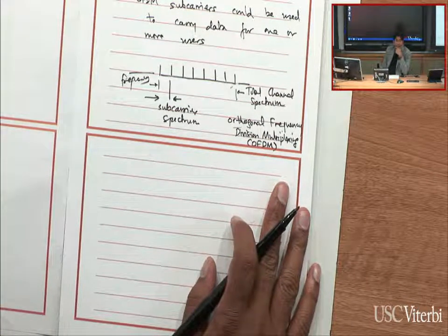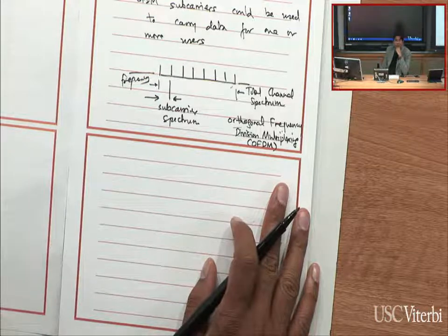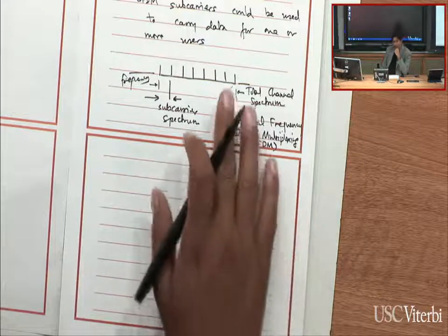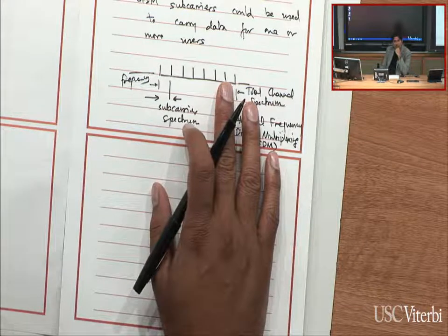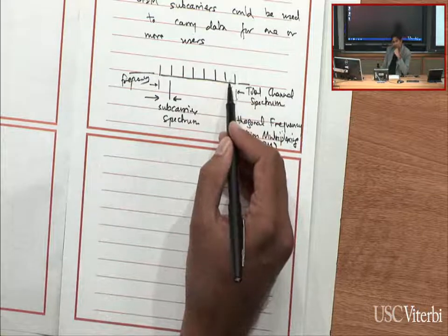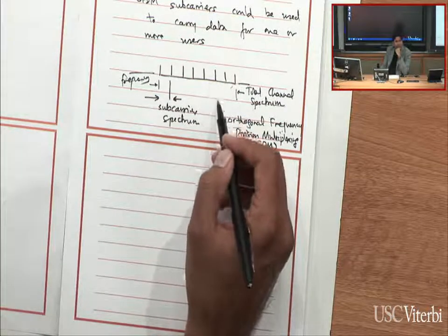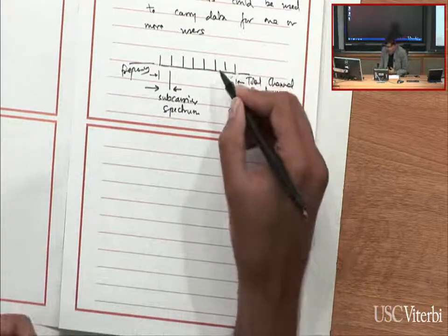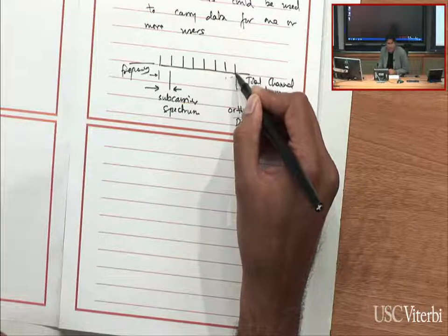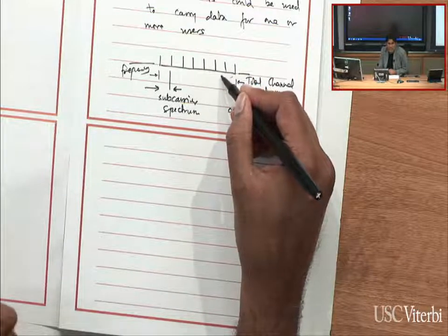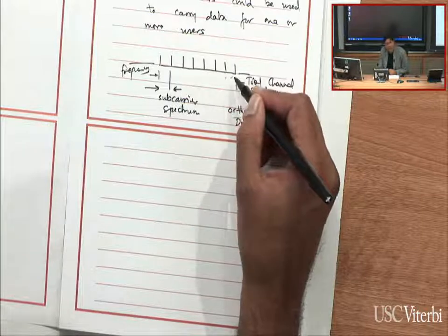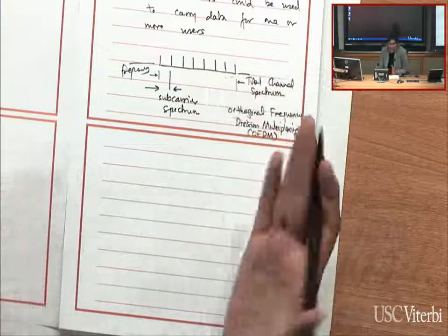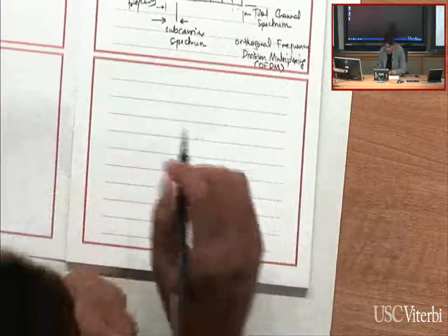And it may have been a marketing term because in CDMA, if your codes are not perfectly orthogonal, they may cause a little bit of interference between users. Whereas in theory, at least, if your transmissions on each frequency are kept within that subcarrier, they really should not interfere with the other carrier. Now, in practice, even that's not entirely true because anytime you're actually sending a signal over a certain frequency range, there's typically some side lobe, some residual bit of leakage of the power from one portion of the spectrum into others. So it's not 100% orthogonal anyway, but those may have been reasons for it.